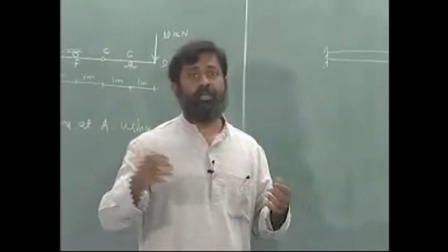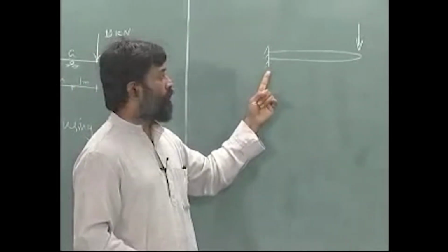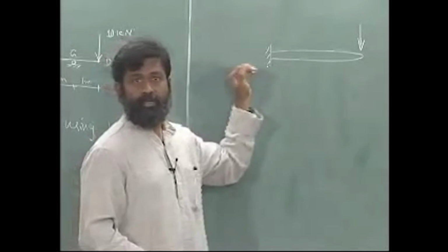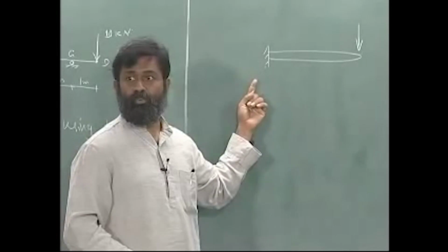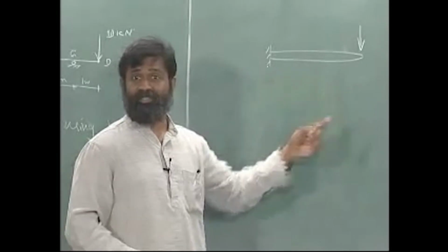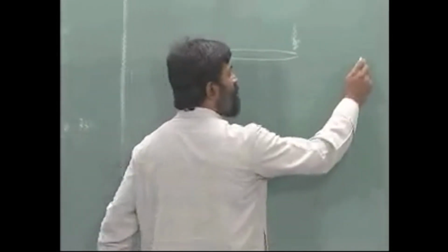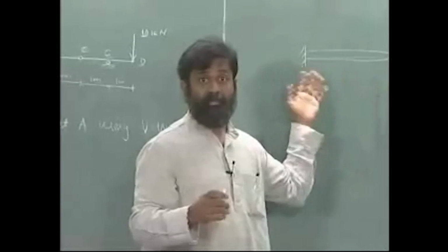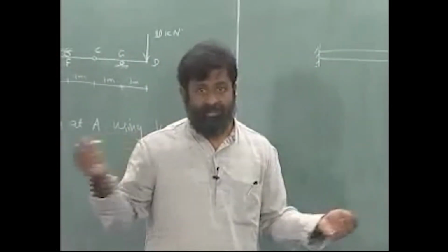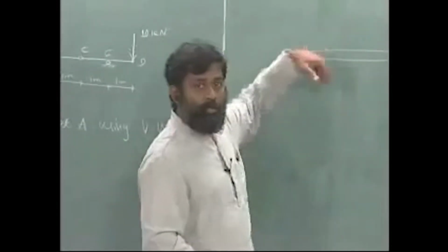Each one of these will give me an idea of what this beam is. Well, okay, there are 2 degrees of freedom. Forget about x, there are 2 degrees of freedom for this rigid body, okay. And if I have 2 constraints for this rigid body, that means the total degrees of freedom is equal to 0, very simple. How many degrees of freedom do I have? I have 3 degrees of freedom for a rigid body. Since this is a beam, one of the displacements, the horizontal displacement, is redundant, which means I will take it to be 2 degrees of freedom, y displacement and rotation.